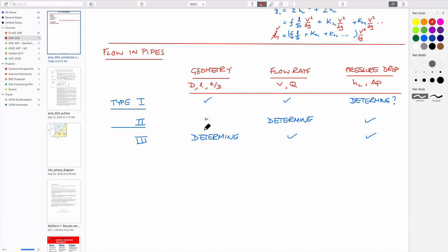The less easy ones, as I suppose I alluded to before, is that the degree of difficulty is in going down in this direction. Because if you're trying to determine the velocity, clearly you don't know the velocity in the first place, and therefore you can't calculate the Reynolds number directly. And so that means that you probably have to iterate in this, and then this gets slightly more complicated because neither do you know the velocity. You might want to prescribe a velocity, but you don't know what size pipe.